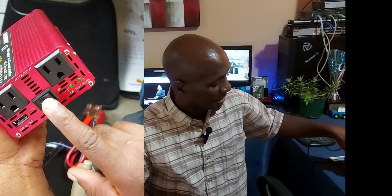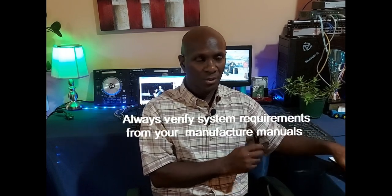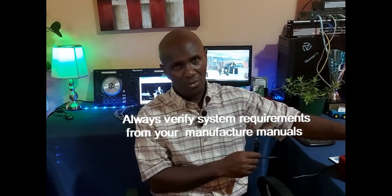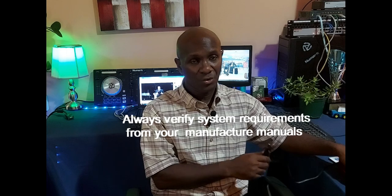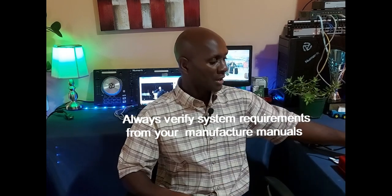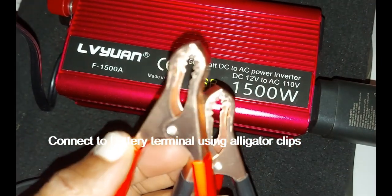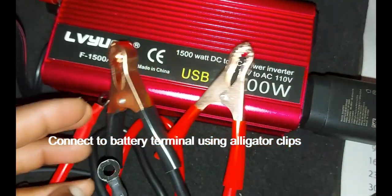And I should also say, and let me just stress here, that when you're going to be using the cigarette lighter to power the unit, it should tip off at about 200 watts. So you should not be connecting any device to the inverter that is going to demand more than 150 to about 200 watts. Now, if the wattage of the device or equipment or appliance exceeds 200 watts, what you need to do is connect the inverter directly to the battery terminal. So you need to connect it directly to the battery of the motor vehicle for that extra demand. Because the cigarette lighter only supplies a certain amount of current.